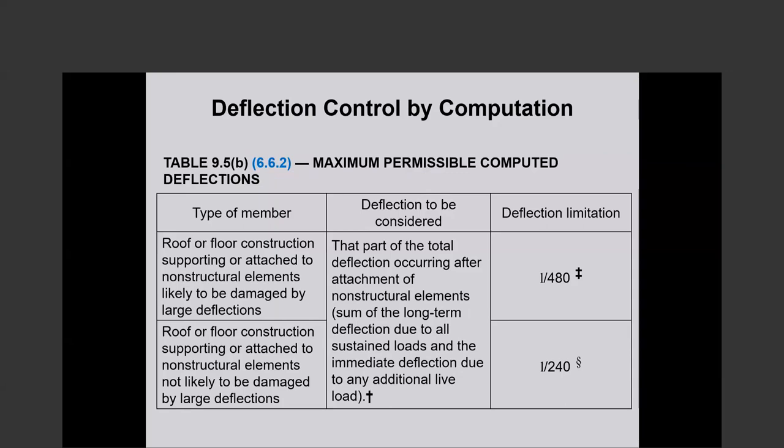So that part of the total deflection occurring after attachment of non-structural elements. As soon as you attach the non-structural elements, there will be immediate deflection due to the additional loads. And so you take that plus the long-term deflection due to all sustained loads. Sustained loads will be dead loads, could be superimposed dead loads, and some of the superimposed live load, whatever is sustained, the long-term deflection due to that.